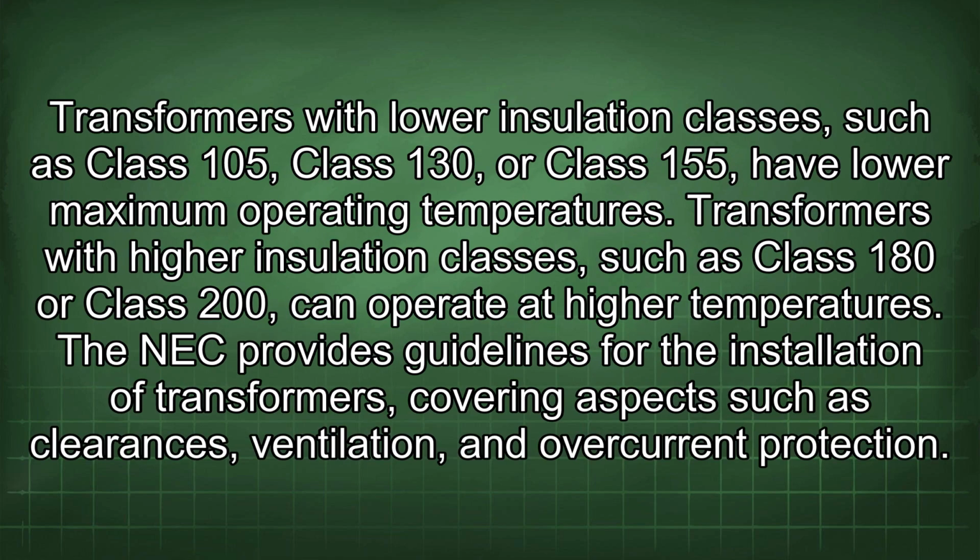Transformers with lower insulation classes, such as class 105, class 130, or class 155, have low maximum operating temperatures. Transformers with higher insulation classes, such as class 180 or class 200, can operate at higher temperatures.